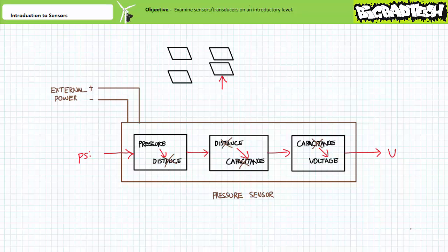I should note that the actual output of various stages of the transduction process are often only very, very tiny electrical signals, and integrated amplifiers, devices that increase the output magnitude, are necessary to obtain usable output. This internal amplification is one type of signal conditioning.